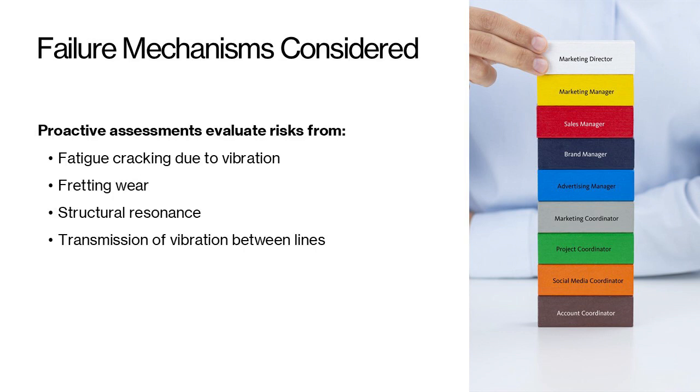Failure mechanisms consideration. Although fatigue is the main focus, fretting and transmitted vibration can also lead to loss of containment or component damage. Proactive assessments evaluate risks from fatigue cracking due to vibration, fretting wear, structural resonance, and transmission of vibration between lines.